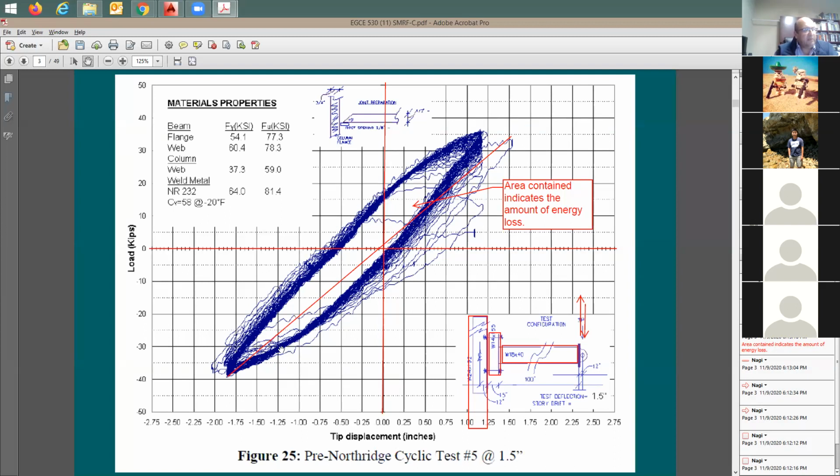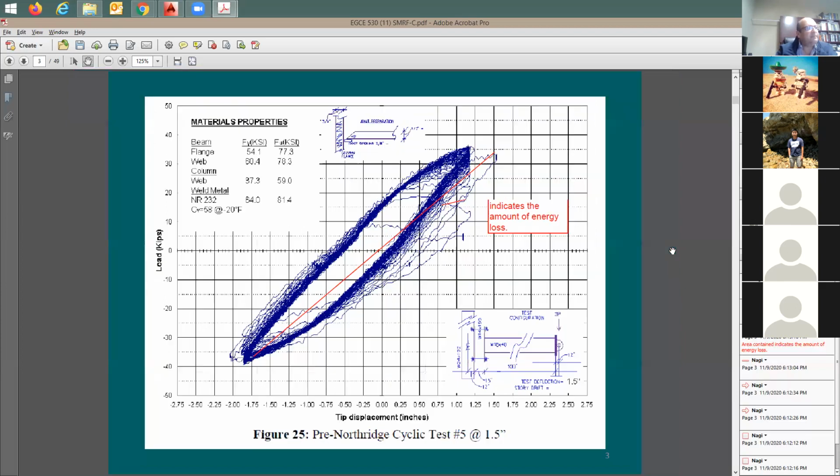Also look at the yield point. I'm guessing the yield point is almost here. This one starts to come down, maybe somewhere in this location. This is going to be the yield displacement, and this is going to be the ultimate displacement. And as you see here, you don't have lots of ductility. So what's ductility? Ductility is equal to ultimate displacement divided by yield displacement. Someone's going to say, if you really give it enough attention, maybe the yield starts at this point. So I'm going to say maybe about 3/4 of an inch for the yield displacement and a maximum displacement of 1.75. Your actual ductility factor is now equal to 1.75 divided by 3/4 of an inch. So okay, good to understand what this is about and the performance curve that we are getting out of it.